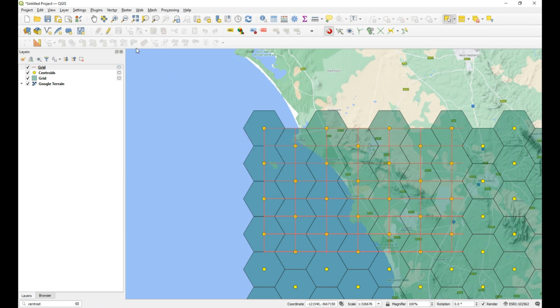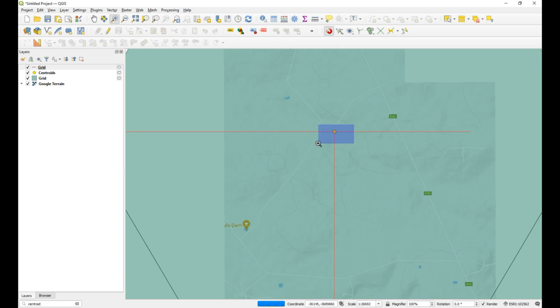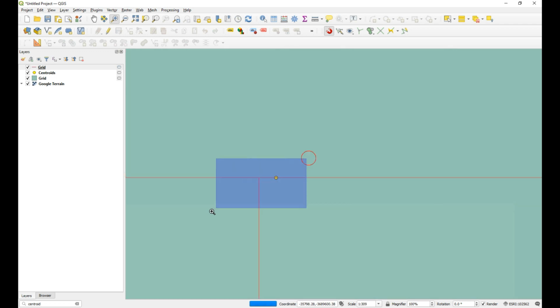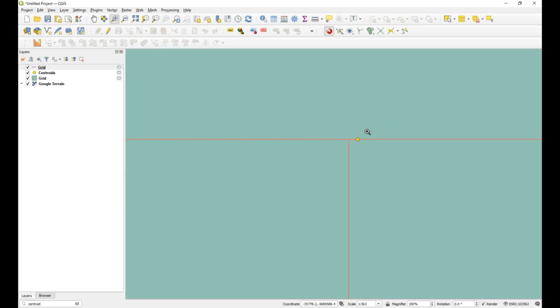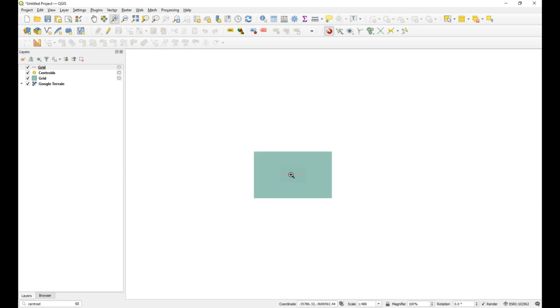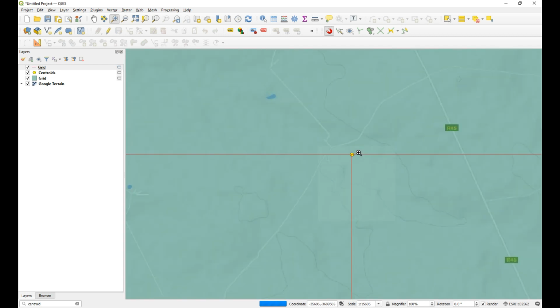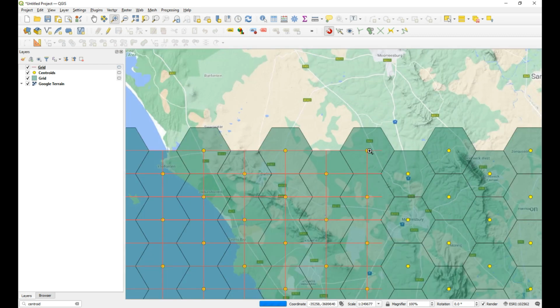Now if you're actually happy with that result and that scale and that accuracy, then your job is done. But if you actually wanted to pass through the center of the centroids, you're going to see that there's a slight issue here. As we get closer to it, zoom in, you'll see that that distance has actually changed. So even though we measured it out up front, the distance has changed. So it's not going to consistently pass through that centroid.